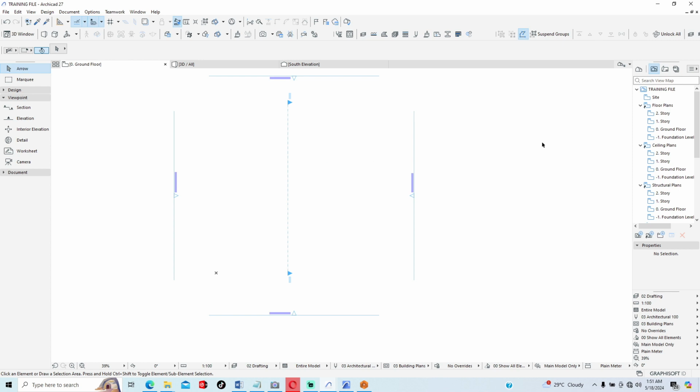But if we want another ground floor plan with no dimension, we can use this view map again to save it as an ordinary floor plan with no dimension. Or if you can see ceiling plan, from this same floor plan, we can save it here again as well. So this is very much important, and I believe as we move along we can understand, because this is in depth, but as we progress we can understand how it works.